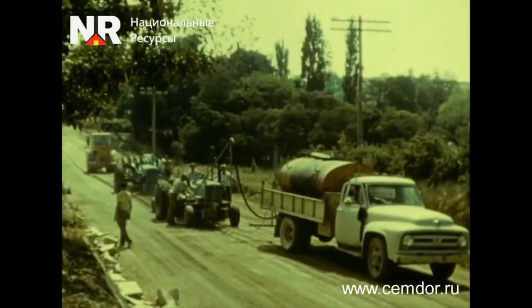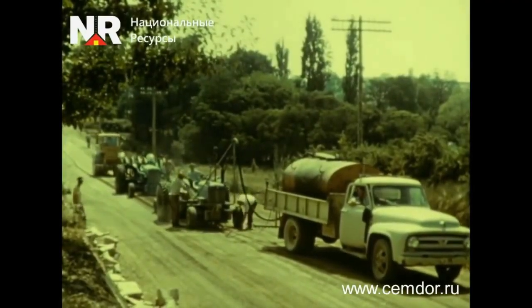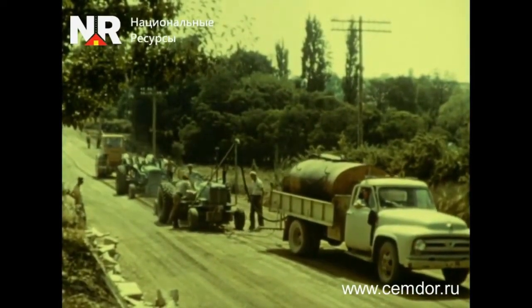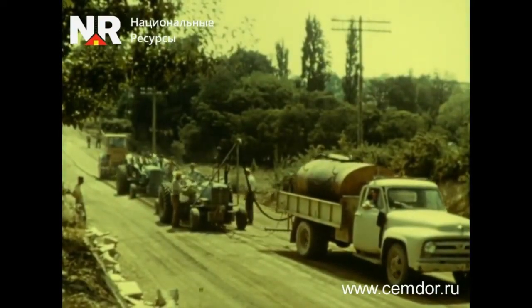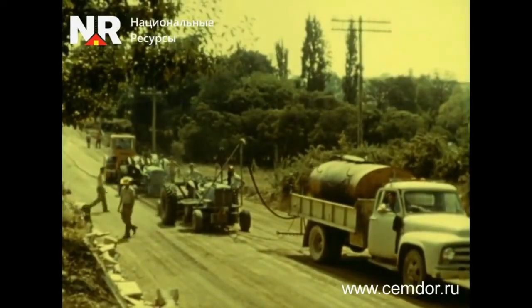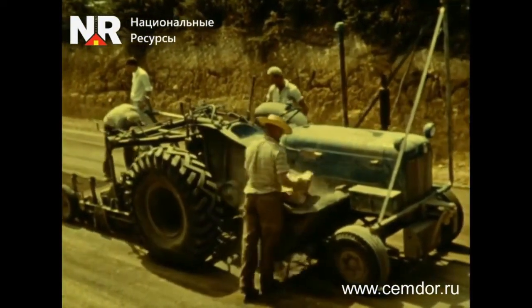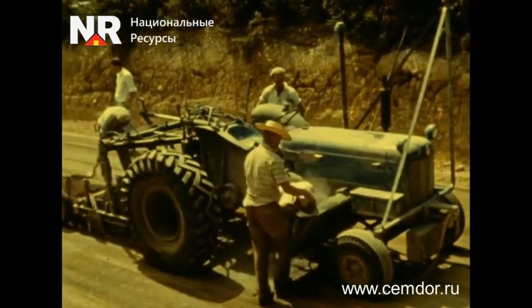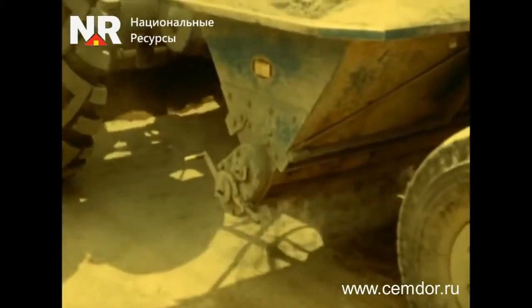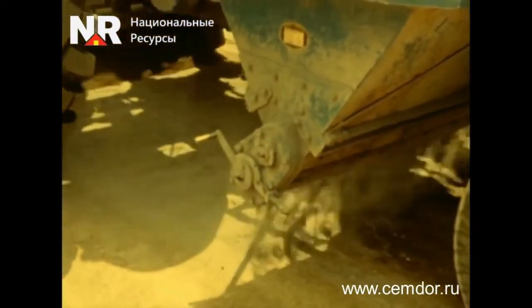Equipment designed to carry out the entire stabilization process in a single pass is known as a stabilization train. It performs crushing, cement distribution, mixing of the soil cement mixture, and compaction. The first unit of this mechanism is the cement spreader, which evenly distributes cement over the surface of the constructed layer, with the required amount determined through laboratory testing based on the example of the soil being used.